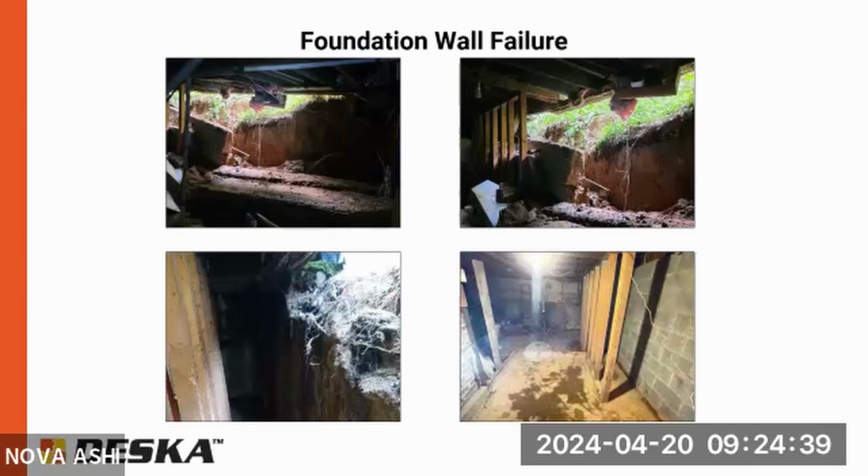In this particular case, what we surmise saved the house above was that little cripple wall there that someone at some point had installed to support a staircase that I guess had some sagging or settlement issues. And without those 4 or 5 studs there, that probably would have completely collapsed. The whole house probably would have.